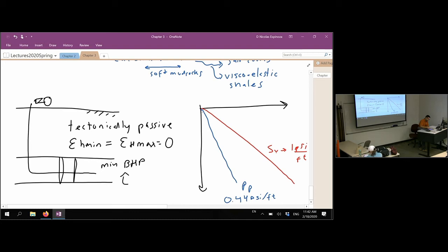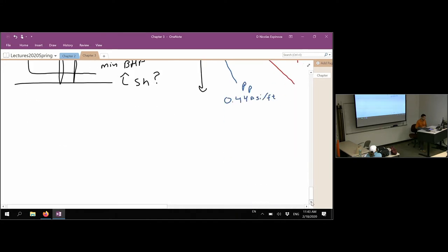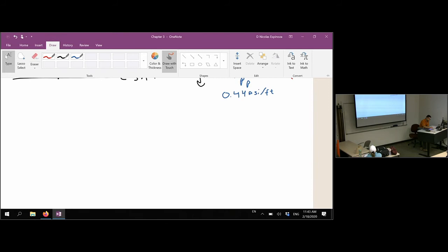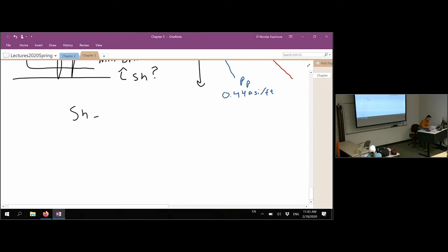Answering this, we're going to have to say what is the horizontal total stress at this place. But now we have the equations for that, and we're going to do that. All right. First, this is just playing with equations. The horizontal stress is just the effective horizontal stress plus the pore pressure, right? Remember, the first one is total on the left hand side.